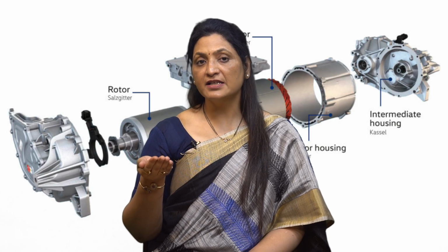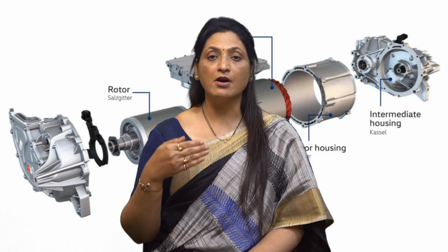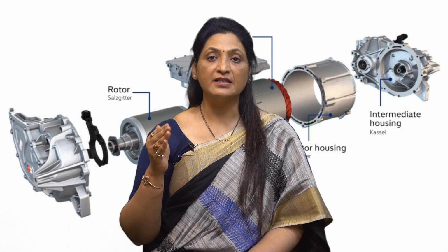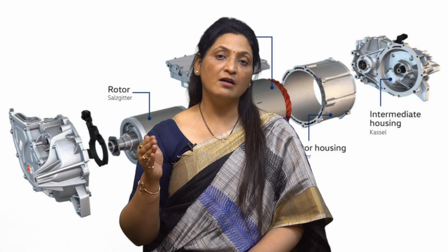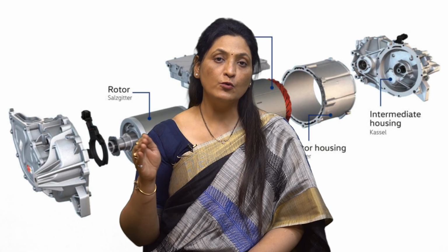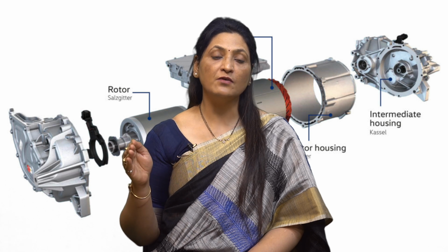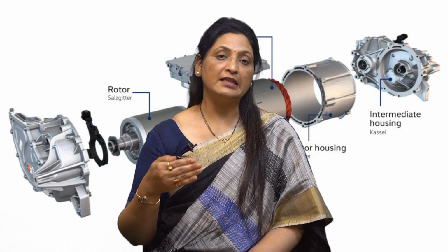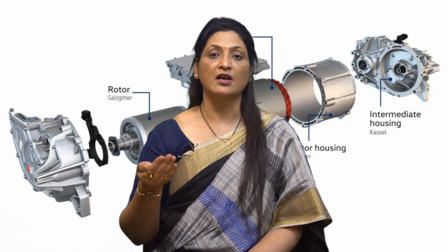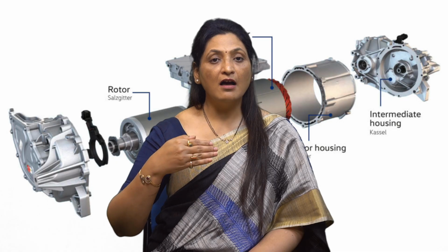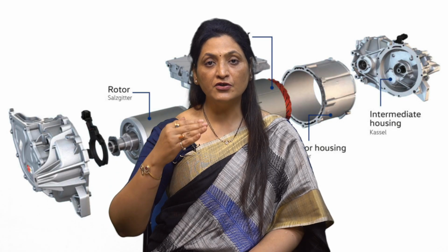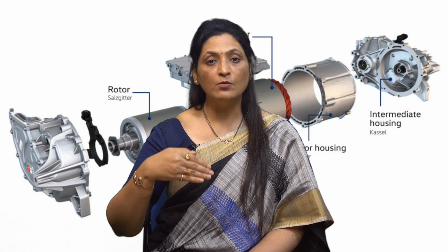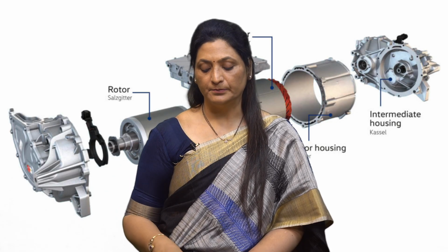Passive torques, whereas, arise due to friction or due to shear and deformation in inelastic bodies, such as lathes, pumps, fans, etc. They always oppose the motion, retarding the rotation of the driven machine. Moreover, with a change in direction of motion, the sense of torque also changes. For example, when a weight is raised upward, the friction torque adds to the useful torque, but when lowered down, it subtracts from the latter.